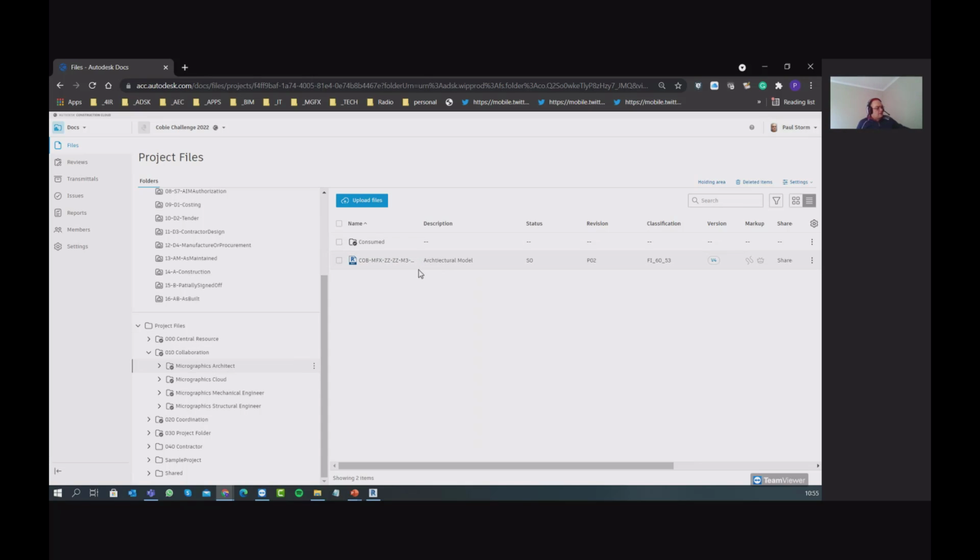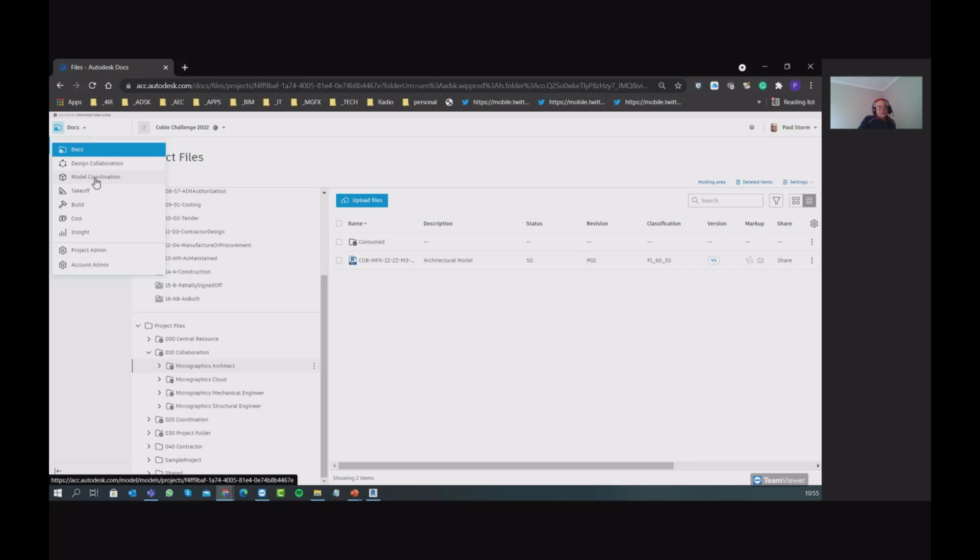And then we typically recommend you do it in a 2-weekly cycle. So 1 week you share with your own team, you try and sort out any clashes that occur, and then the next week you do an interdisciplinary clash detection meeting. So you can also create some model coordinations. So that is where you do clash detection automatically.